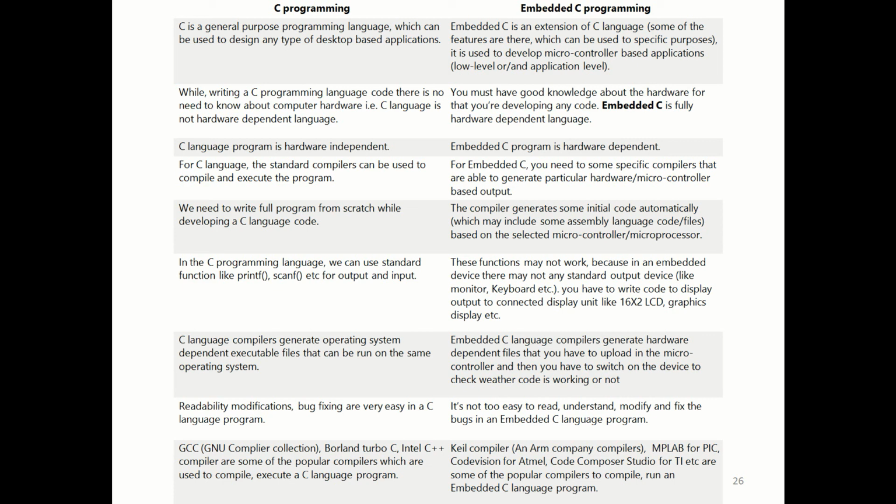Several companies, several CPUs. So when you write a program, your embedded C belongs to which company? It is not the same. Company to company, the embedded C compiler is different. Target CPU is different. Peripherals are different. So slightly the functions won't be the same.